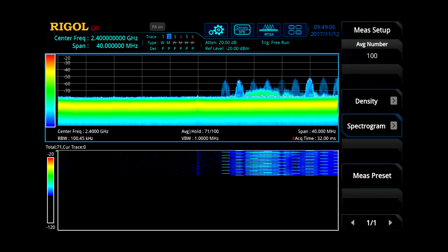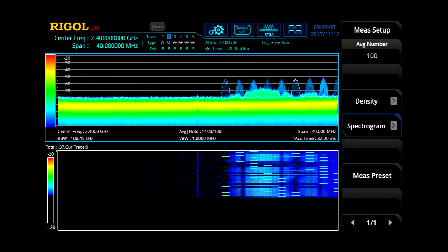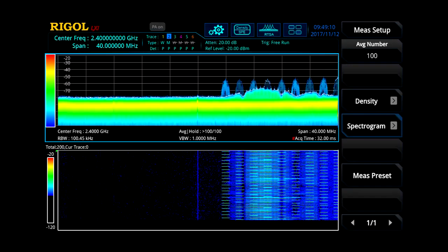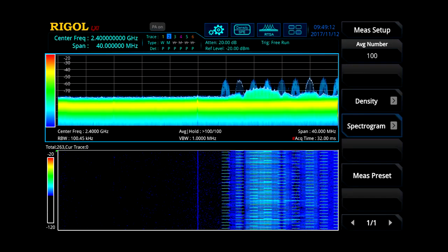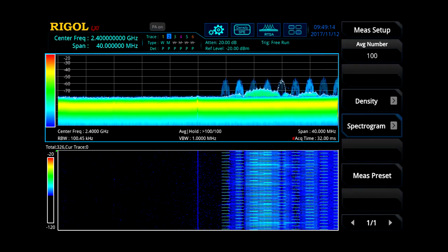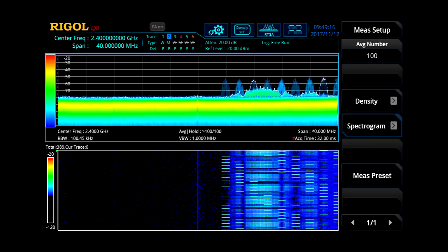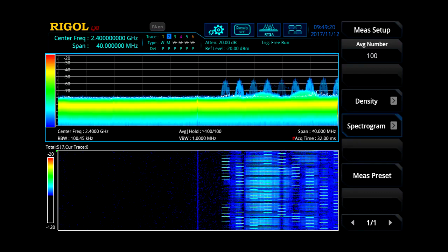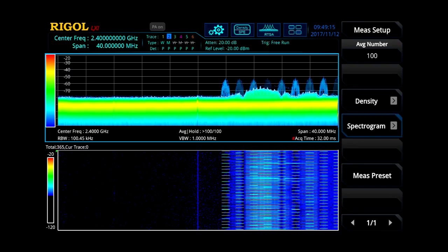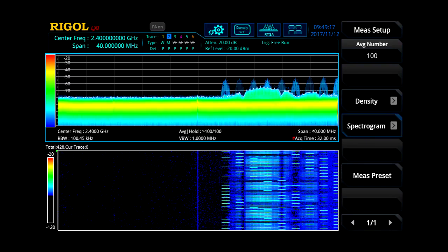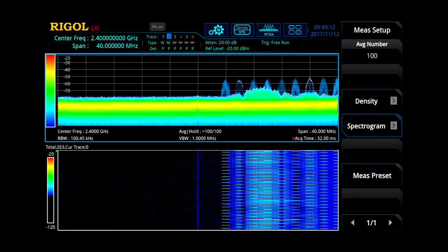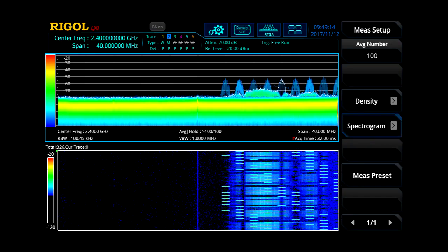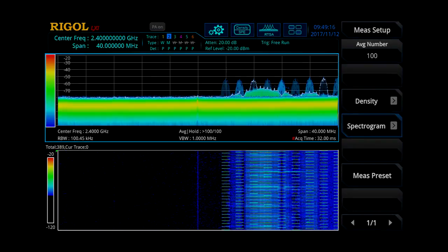Real-time spectrum analyzers call the ability to capture short-duration transient signals the 100% POI, or probability of intercept. It is measured in time and indicates the shortest signal that is guaranteed to be captured. The RSA5000 can be set for 100% POI as short as 7.45 microseconds. This is accomplished by the calculation of more than 145,000 FFTs every second within the instrument.